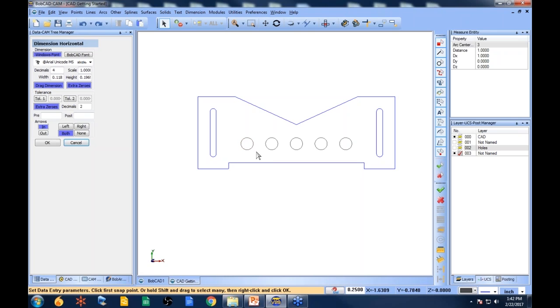So I hold down Shift, one of your keyboard tools, so Shift, left click on the arc, and then you get all your snap points. From there you can click on the point you want to measure off of, and then Shift, left click, and then you can grab another snap point. Now, you do get snap points from surface edges and solids, so you can use them for translations. You just don't get all the snap points for a circle because you don't really have a circle. You have a spline, so it has 1 point for circles, okay?